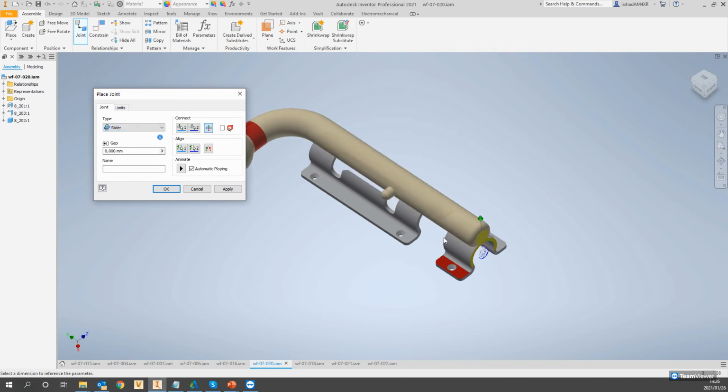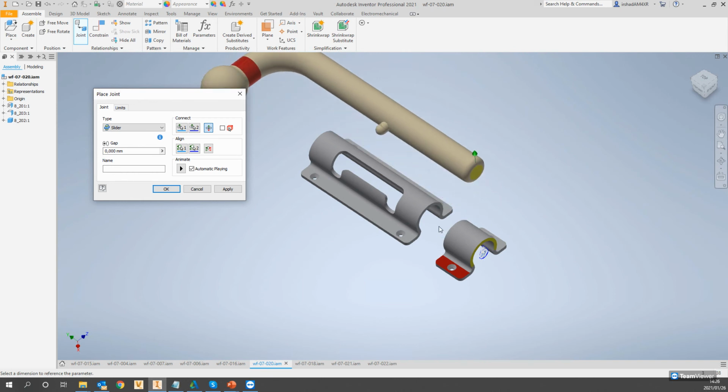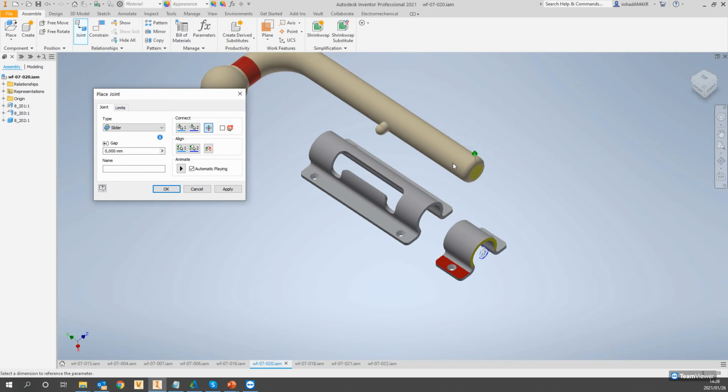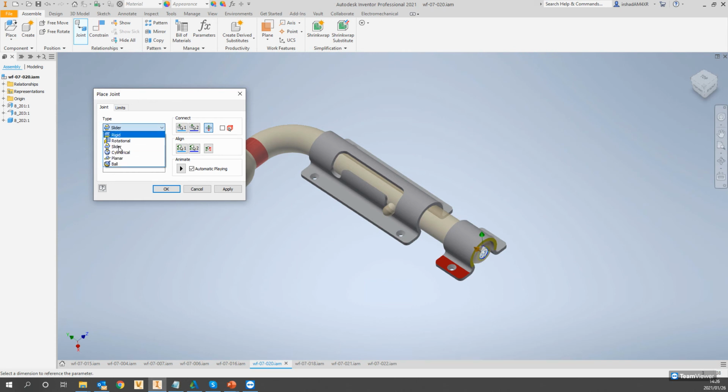This might not work very well because I've chosen two planes that are not ideal, but you can see it's detecting sliding in one direction. Although this is not ideal because it's using the planes that I selected to slide either up or down or maybe left or right, and not the cylindrical plane. If I really wanted to insert this in, I would of course use the cylindrical setup.